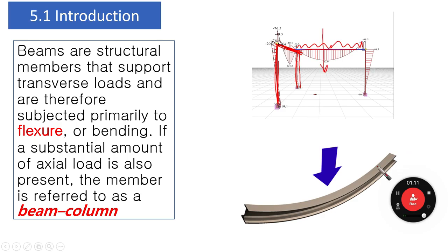So whenever we are going to find how this beam is going to bend or deform, we're going to find that it is going to deform in this way, as you can see, because all the loads are coming vertically on the cross section, so it is going to be under flexural bending and it's going to deform in this way.